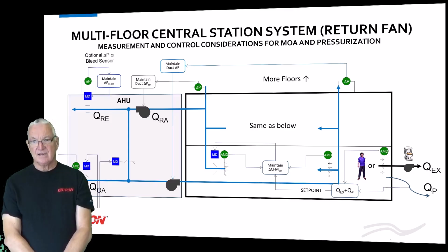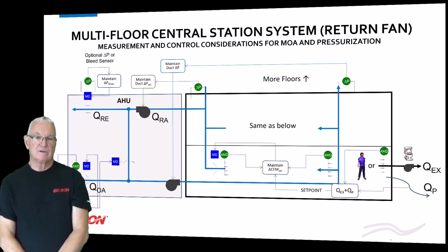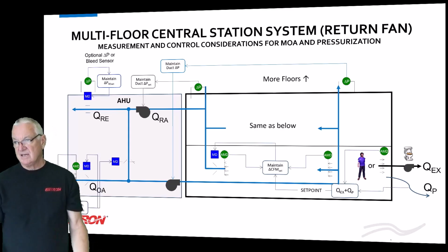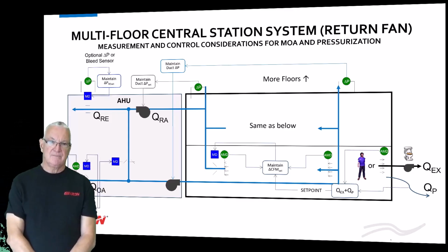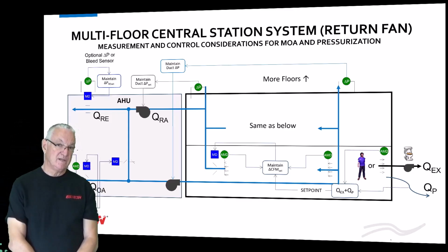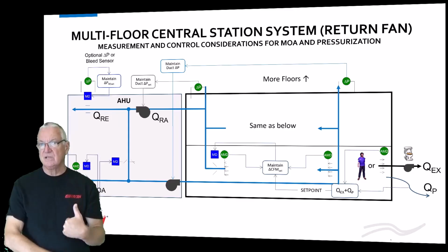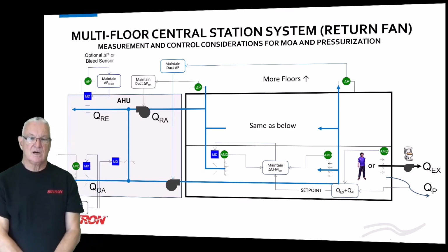It's not accurate enough to do that. Put a flow meter in the total supply. It might be more than one flow meter. Put a flow meter in the returns. It does require some kind of ducting or stub ducts. Our IQ product is actually pretty good for the return side. But you get this flow differential. You may have to change this offset throughout the year to compensate for stack effect and vertical leakage of the building, but you can pull this off.